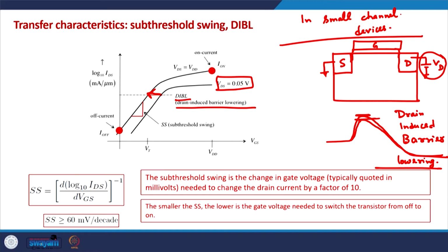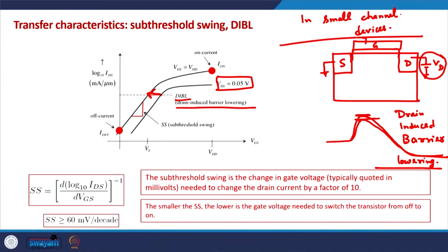Generally, prima facie it would seem that this is a good effect. We now have less threshold voltage, the channel appears faster, but that is not the case, because it is interfering with the role of the gate terminal, and it is actually giving uncertainties in the device.